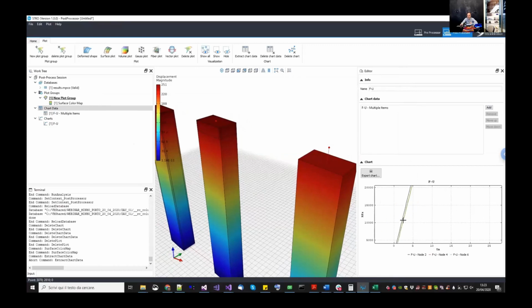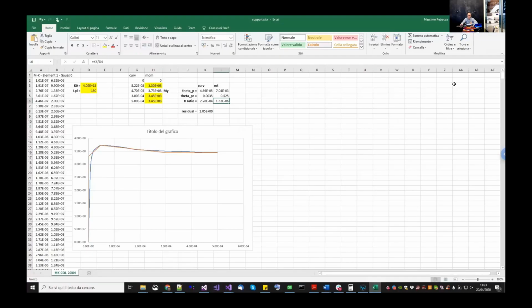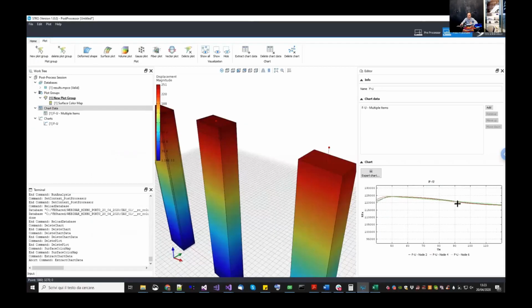Of course, the green one overlaps better with the red one, which is the one here, because they share the same elastic reduced bending section here. And of course, here you see how you can get the peak strength, because we calibrated it on the moment curvature obtained from the distributed approach.